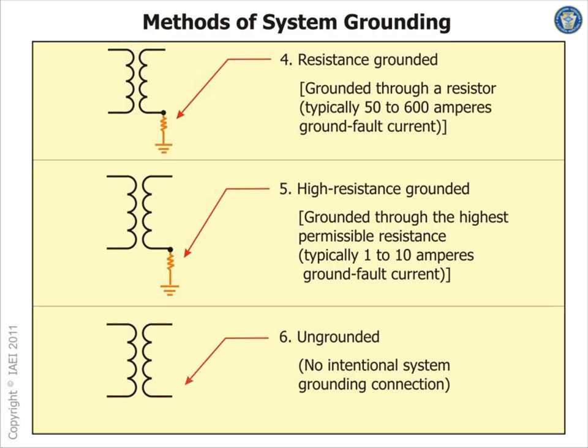If you have a ground fault on an ungrounded system, you have a transient voltage that hits the panels, and that transient voltage can burn my laptop and your phone right here. If the system is impedance grounded, you can control that current going to the ground. When I say control, you control it so that you don't trip the circuit breakers, so you don't interrupt the process of making canned beef from a cow, and at the same time eliminate the hazard associated with the transient coming out of a ground fault.